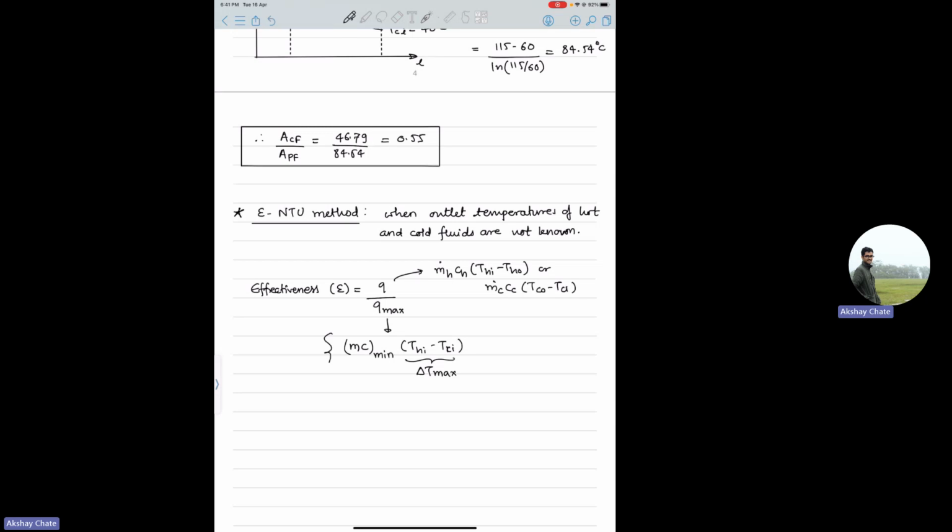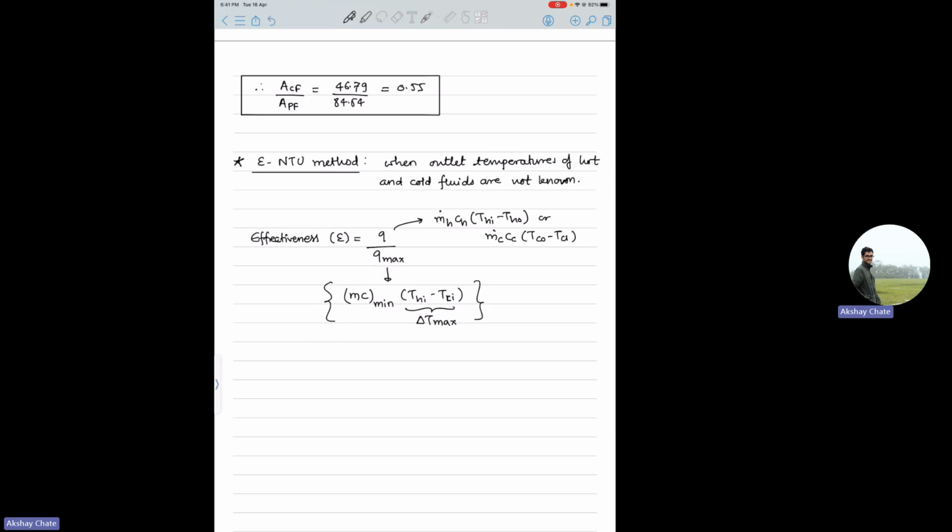So this is also a very famous question. Sometimes in GATE directly this formula is asked, and people usually get confused with this. Typically what we think is to have maximum Q, we should have maximum delta T as well as maximum MCP. Delta T is maximum, fine, but MCP, if you have maximum, you will not get maximum delta T, because these two things are inversely related. So therefore you should have minimum MCP and maximum delta T.